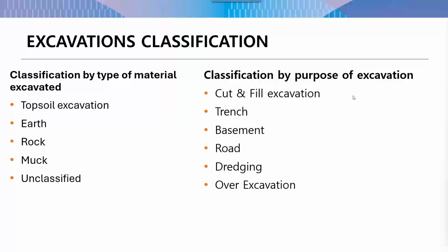Coming to the purpose of excavation. If we classify excavation based on the purpose it solves, first is the cut and fill excavation. You might have seen it in urban areas, especially where a subway station has to be built. Sometimes we dig the area and then it is backfilled along the precast segmental liners.